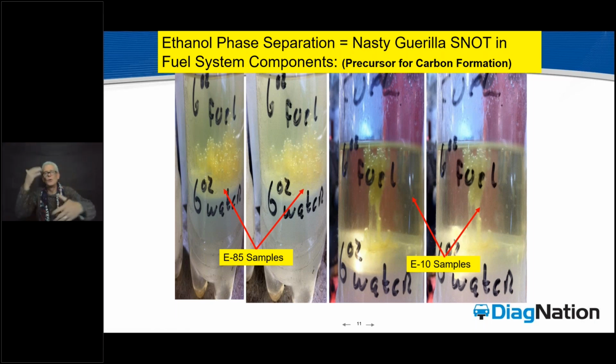But as this fuel sloshes around in the tank, this oxygen is being infused. It is reacting with the water molecule, it is stripping the paraffin, and it is slowly pulling it to the top. Now, the big thing to remember here is two things, guys. If you consider this area right here to be the bottom of the fuel tank, because this fuel is always going to ride right at the water interface, and there always is a water interface in the tank, even if it's very minor, okay?